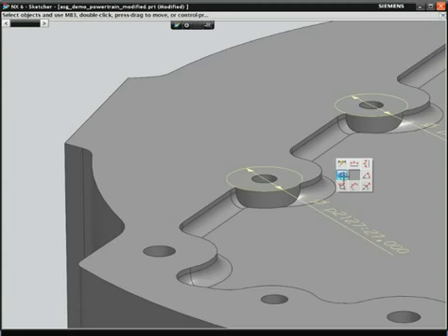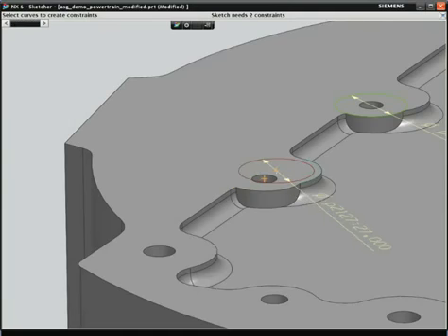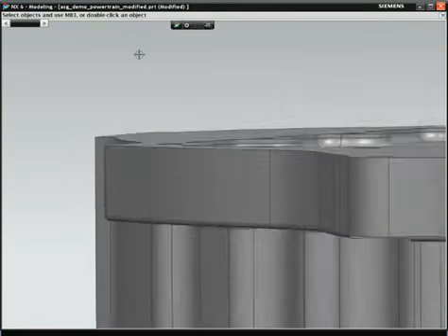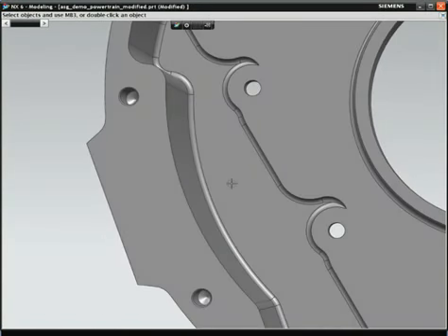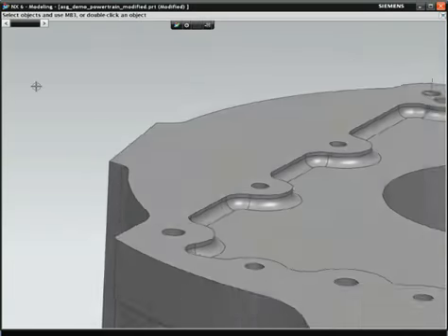To achieve the desired result, you need to assign additional constraints to the sketch to center the holes with the bosses. With the modification complete, you check the other side of the part only to find that there's a problem with the bosses on this side. If you had time, you could go back to the part history to determine how to make what appears to